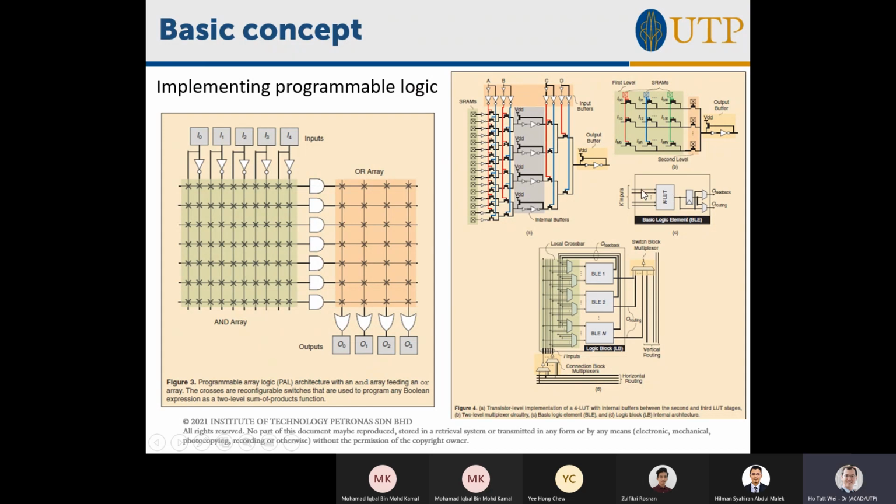This lookup table implements a function taking K inputs and producing a 1-bit output. K is normally 5 or 6 in an FPGA basic unit. It's connected to a flip-flop here, and it can either bypass the flip-flop, or the output of the flip-flop can be fed back, or the output can be selected between these two, either going to the output or routing.